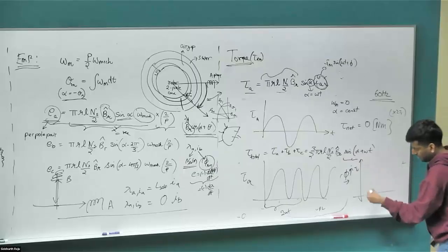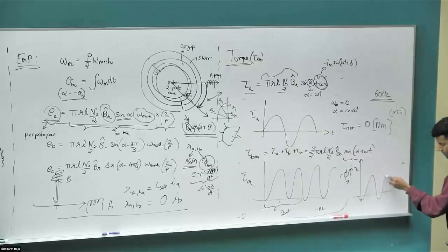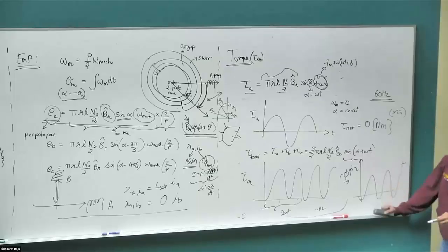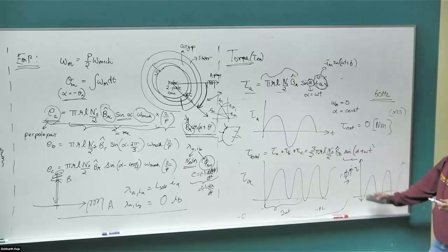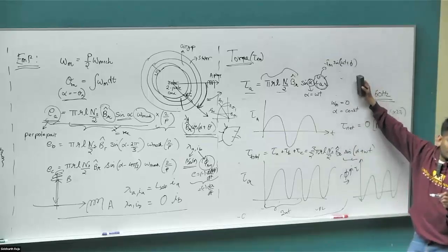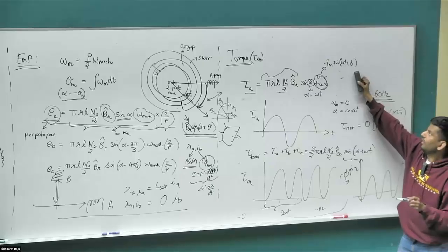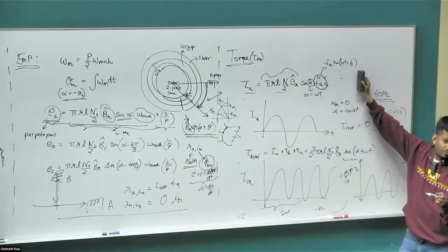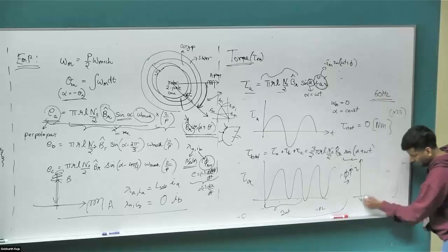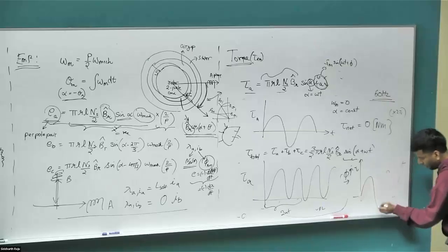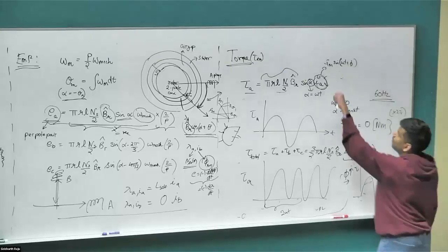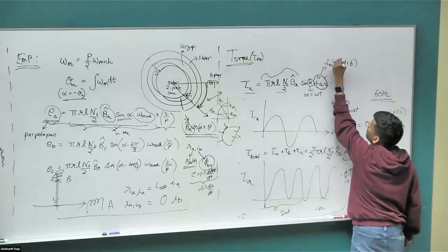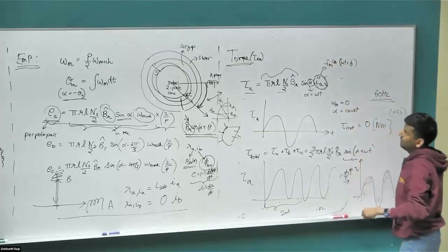This torque waveform is going to have some negative component, some positive component. Right? So the real power effectively came down in our AC circuits. In this case, the torque is going to effectively come down. When this phase becomes 90 degrees, you would end up with the product of cos times sine, which would have equal area on the top, equal area on the bottom, with the net torque being 0. Alright, so let's go back to our original equation. Cos of omega t. Right?